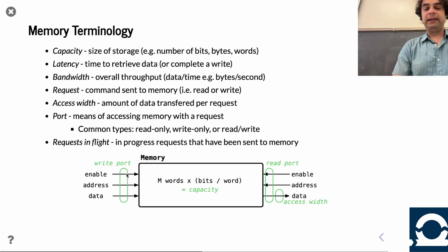Sometimes the memory technologies have a limit to how many ports they can have, right? So, for example, in DRAM, you typically have one read/write port for an entire, at least MAT, this is terminology deep inside of DRAM. At the higher levels, you can definitely make it seem like there's a lot more, but at a MAT level, you basically have only one read/write port. And SRAMs in the CPU, you can have one read/write, maybe two read/write ports. You can go higher than two, but usually it's pretty expensive. And so there are various constraints. On FPGAs, using BRAMs, you get two read/writes, etc.